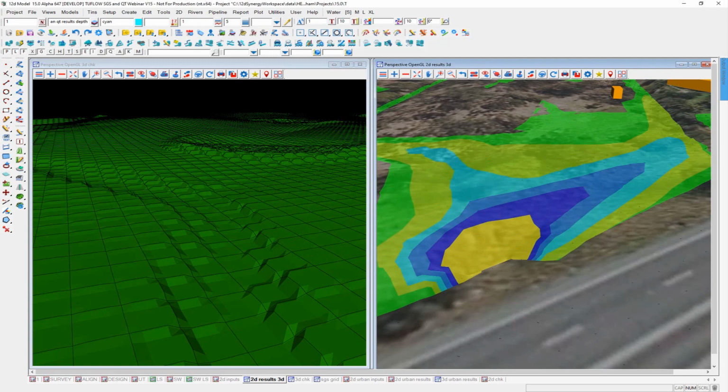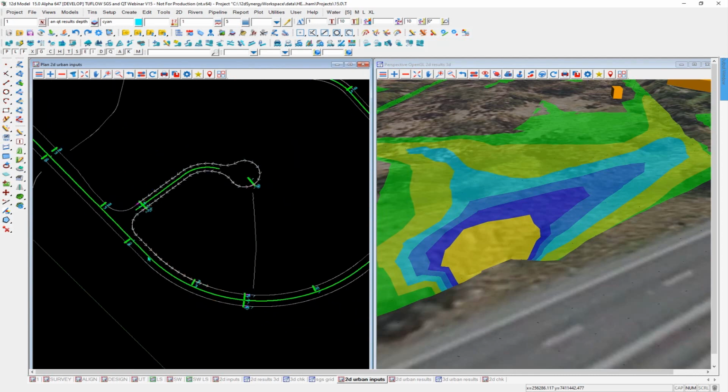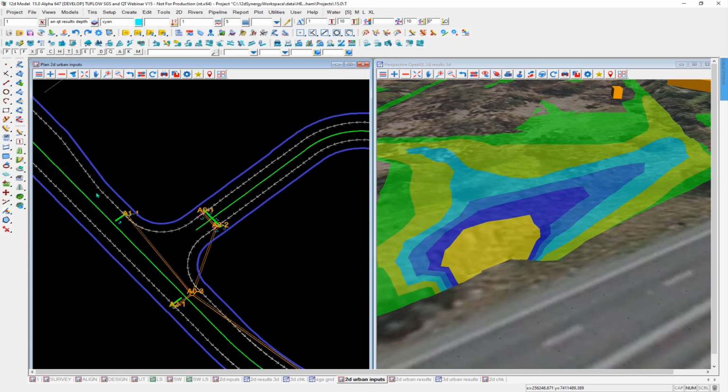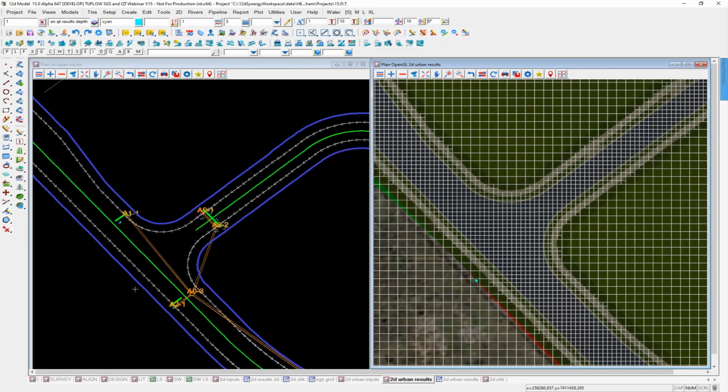And now what I'd like to do is bring up another example of an urban area, and we'll use that urban area to discuss Quadtree. So I'm going to do my 2D urban area, and typically, once again, we would have an extent rectangle around the edge. But if we come in closer now, we've got another polygon we can specify where we want to have additional smaller cells, so a Quadtree refinement. And if we go take a look at what that Quadtree refinement would look like, if we come across here, you'll see that inside that polygon, you can probably see the cursor over there moving on the left, that cross.